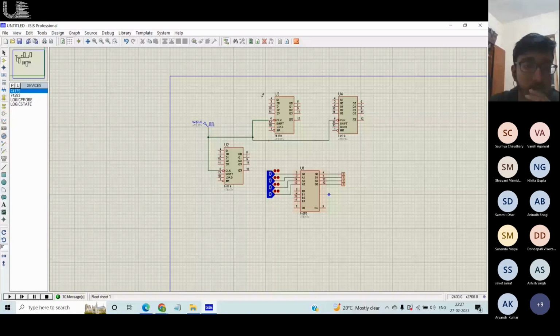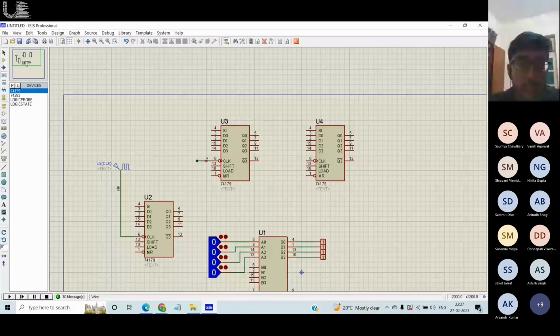you put in a thing called a label. Okay, go to variable section, just click on this wire anywhere you want. Okay, and just type in, say maybe I'll give it a name of clock. Okay, so this wire has a label of clock. I can just make a dummy wire here and click on this. You can see a small cross on the cursor whenever this label mode is selected, and you can just type in the name of the label that you want it to be, right? So the value here becomes the value here as well, right? And it looks so much cleaner if you notice, right? So to see this clock here, it's also feeding in 0101, you can see, right? So that's one trick.